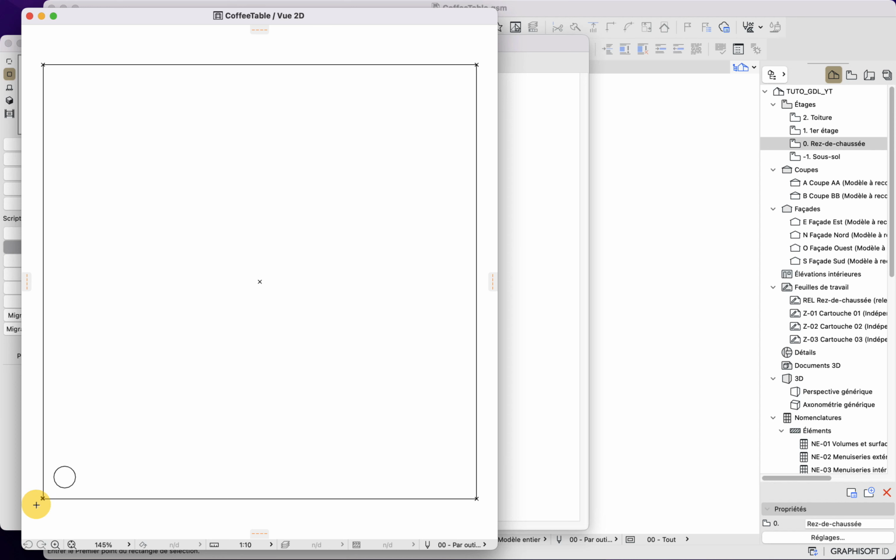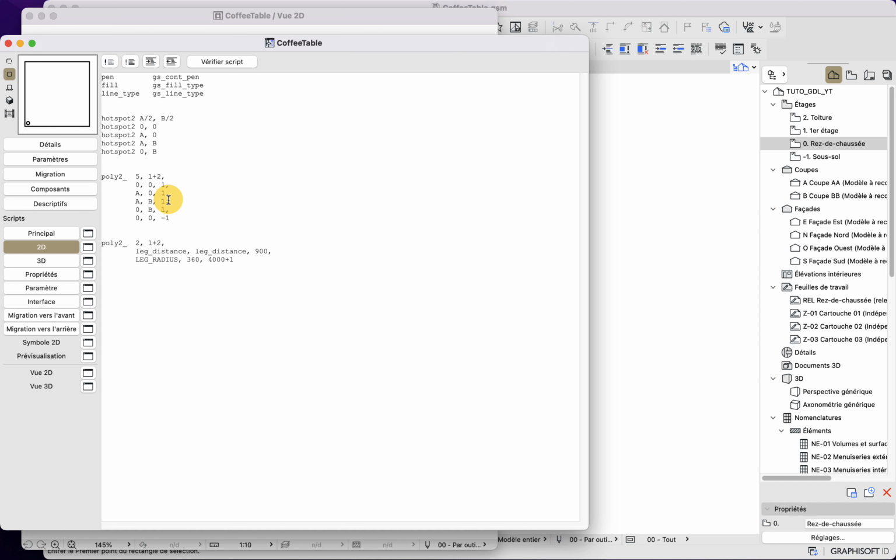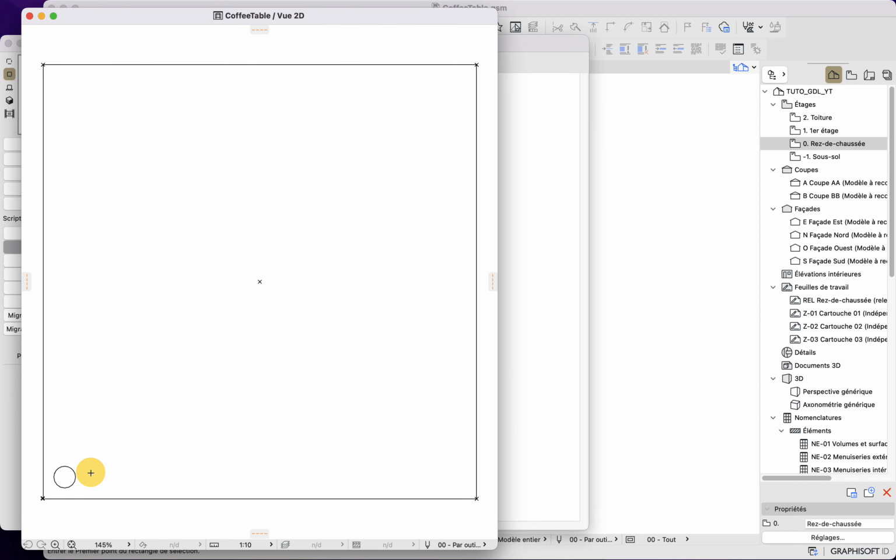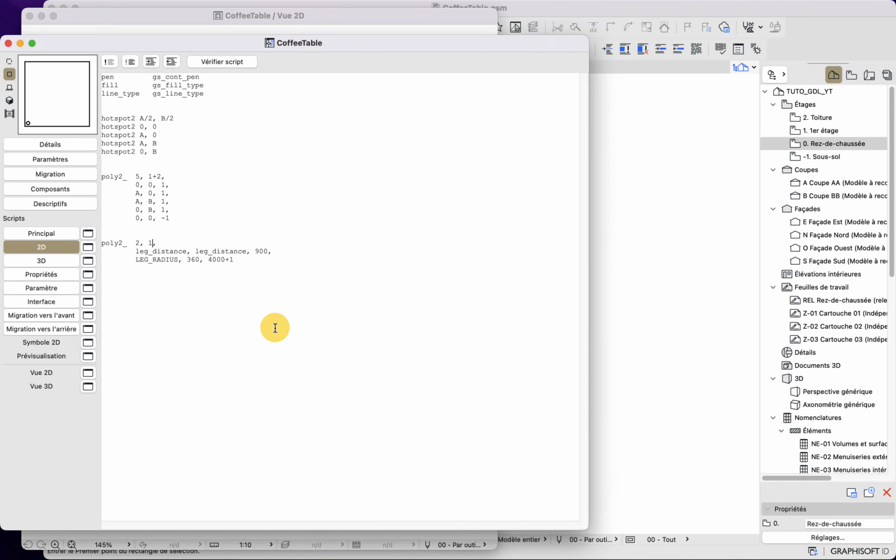Also, you could see that there was a fill in that leg. It is not useful because there is already a fill here. So what we will do is delete the fill by simply putting 1. Now, if I go back, there will be no change, but that way we do not generate any kind of fill, so we do not have a fill on another fill. It would be stupid. So here you can see that it works well, and I can create new legs at the other coordinate points that are needed.